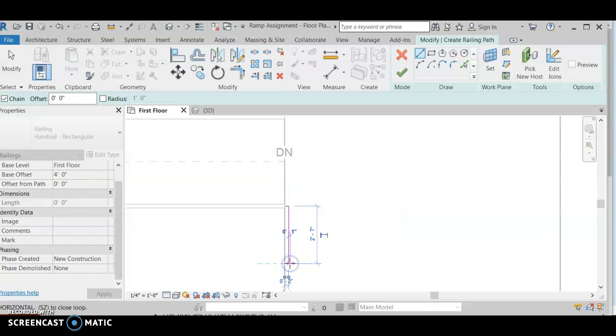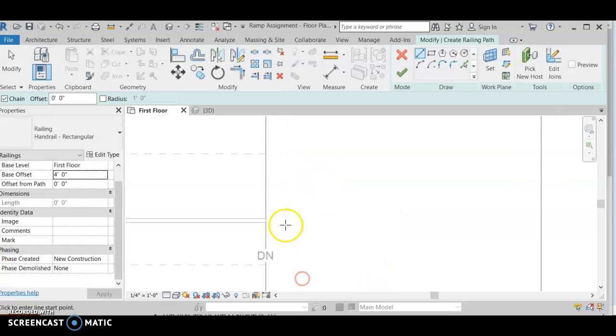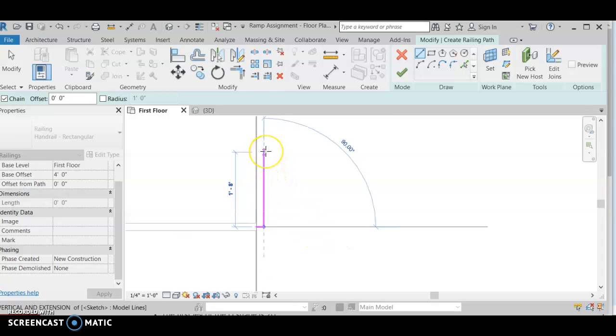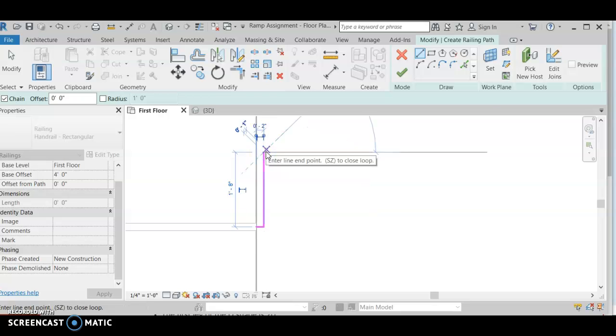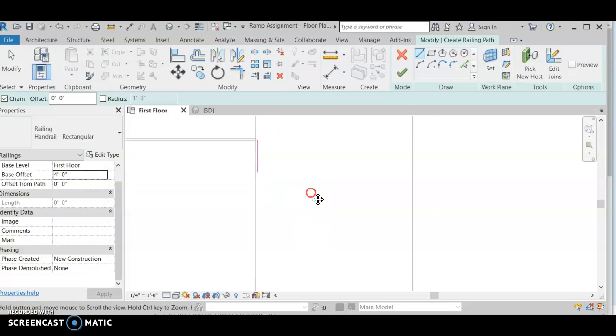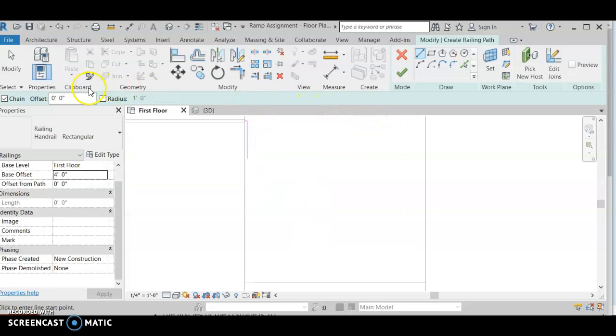We're going to do a trim extend so we don't have to worry about getting it perfect yet. Now let's draw another line in the middle of this one. Come out 2 inches, not feet like I usually do. And then once more, just turn the corner and we'll do trim extend. And since in Autodesk world they like to do things counterclockwise, I'm going to now set the offset for 2 inches to match what I did up there.